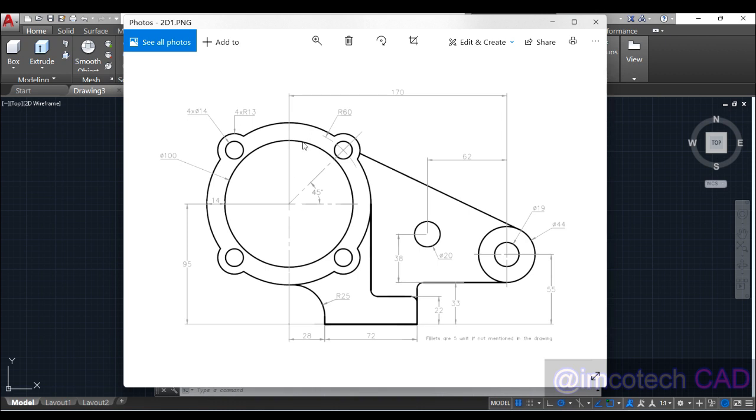You can see we have a circle here and another circle here. The diameter is given for this one. Also, for this inner circle, used to get the center of this little circle here, the radius is given. As for this bigger circle, the outer circle, we have the distance between these two circles as 14, meaning the same 14 will be here. So we're going to add 14 and 14 to this diameter, which is 128 units.